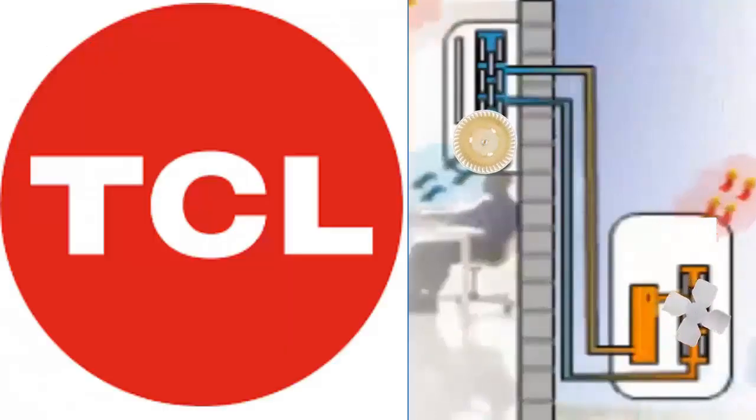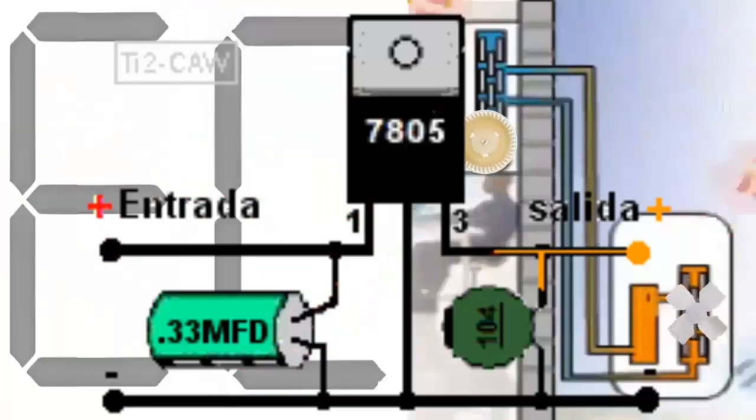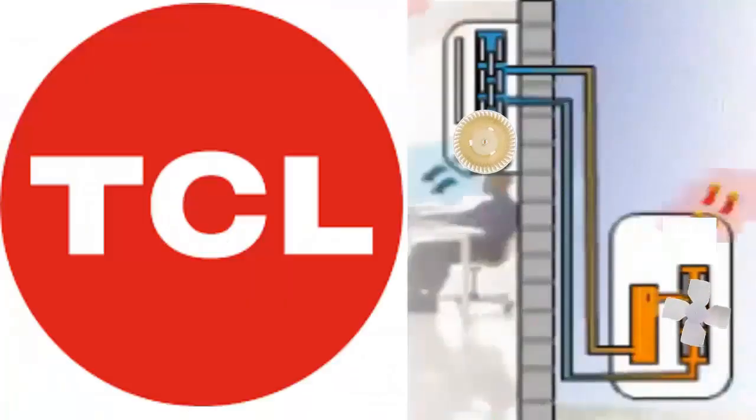7. To check a specific electronic module, verify the presence of voltage at the connectors. Refer to the data for each connector. Sometimes, the issue lies with the electrolytic capacitors or the voltage regulators. For example, a voltage regulator labeled 7805 should output 5 volts. Check for faults in the PFC circuit, following the recommendations that we will see in the next steps.